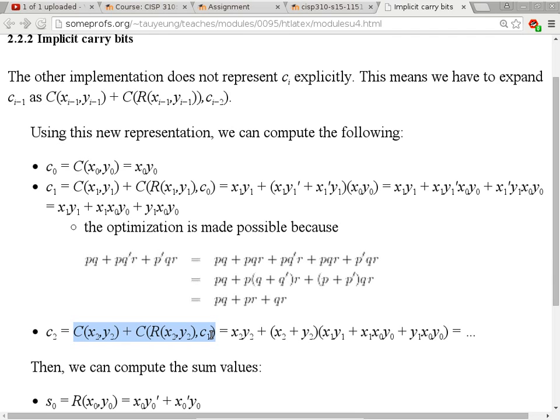But you can also see the problem with this one is it does get a whole lot more complicated. This is just bit 2. What about bit 63? Yep. And that's why this is not done by hand. If you work for Intel and you ask the person who designed the adder part of the 64-bit processor, it's not done by hand at all. It is done by a program. The program will automatically give you the equation, and it will go through an automated optimizer to optimize the equation to use the least number of gates and do it as quickly as possible.